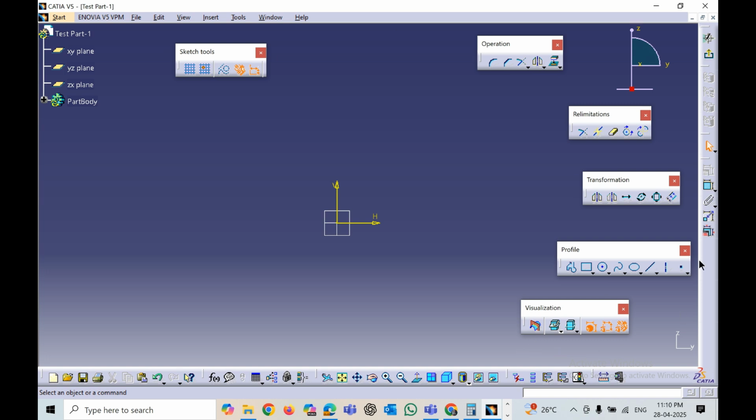Now, in case we have mistakenly moved it, you can see in the Sketcher workbench itself it has been moved to a 3D space. You can see all three planes. In order to bring back the XY plane that we selected earlier, there is this option known as normal view. Just select it, and it goes to the normal position.